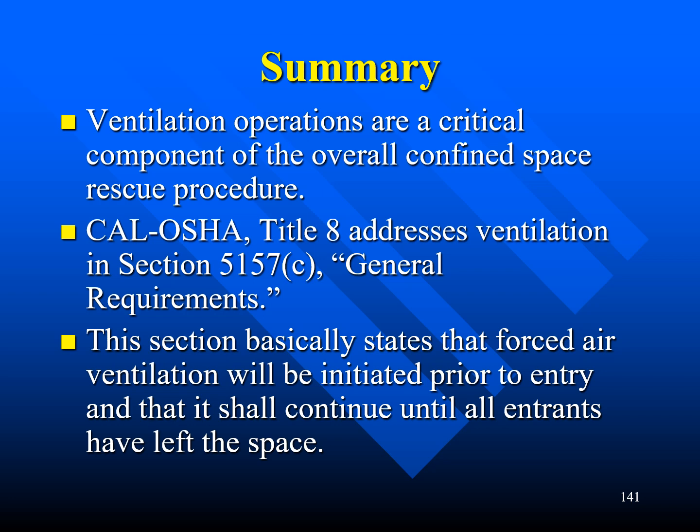Let's summarize this lesson. Ventilation operations are a critical component of the overall confined space rescue procedure. Cal OSHA Title 8 addresses ventilation in Section 5157C of the General Requirements. This section basically states that forced air ventilation will be initiated prior to entry and that it shall continue until all entrants have left the space.